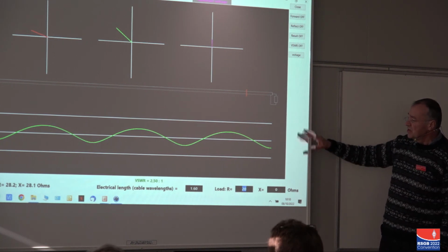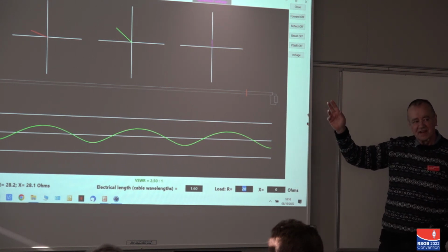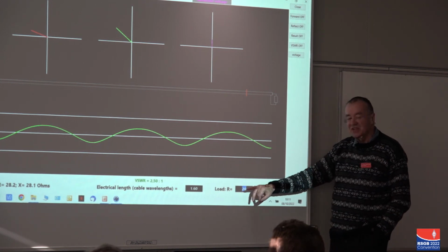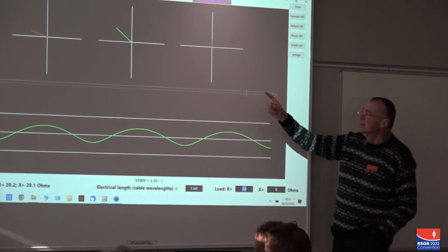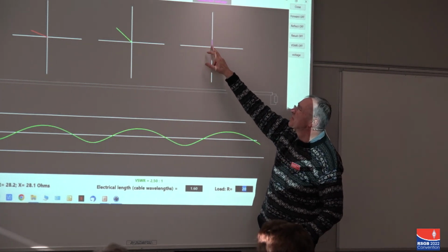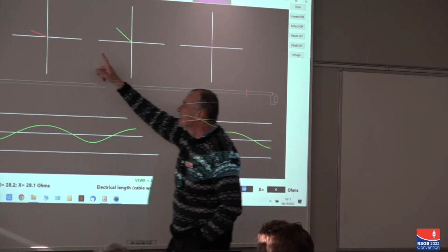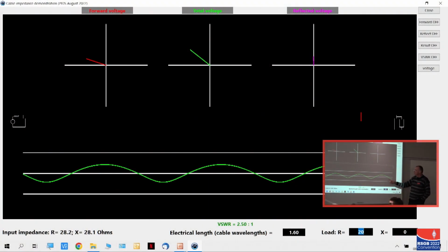And you can see that you are now transmitting something in your 20 ohm antenna. I was going to say the radiation resistance. Well, it's some of various things, but that's going on there. And so the amount that's actually reflected is smaller. So the amplitude of the reflected wave is reduced. Here's the forward wave. It's still the same length, but the reflected wave is reduced. And that means that it's not perfect reinforcement and it's not perfect cancellation.